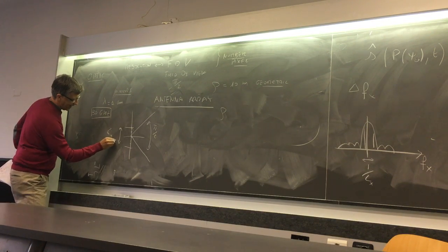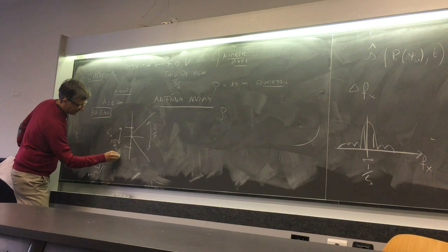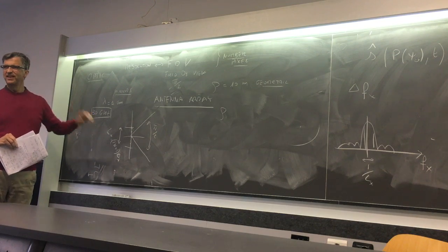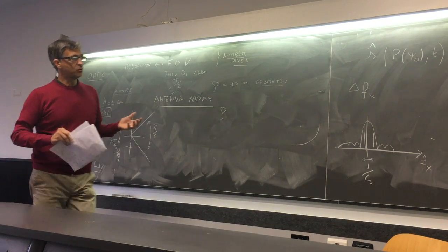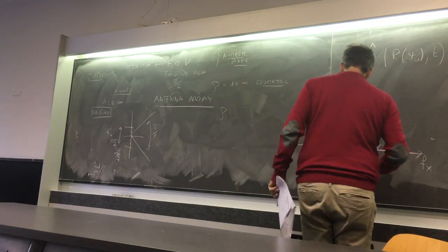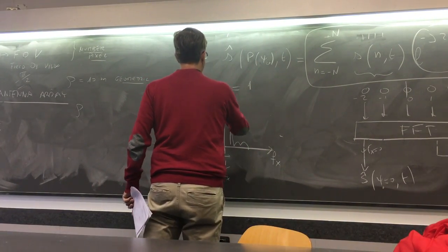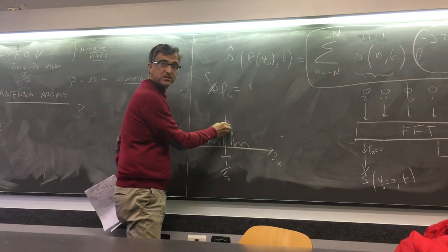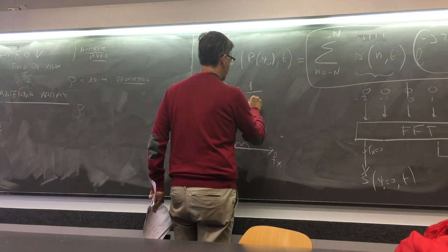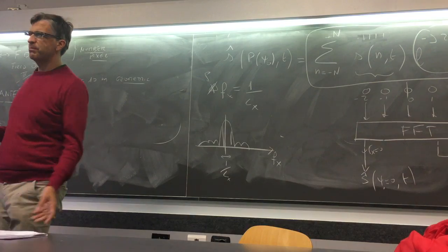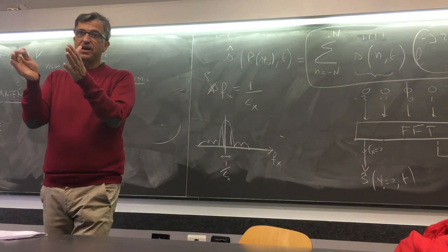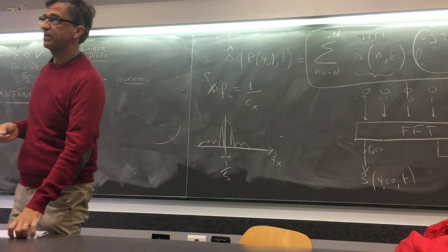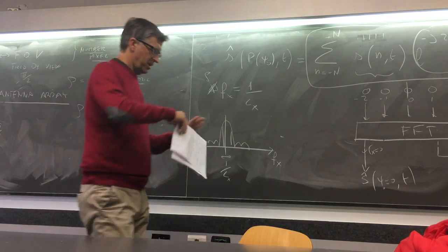It is equal to 2n plus 1 multiplied by delta x, the total number of antennas multiplied by the spacing of every element. Okay, you remember? So the resolution, let's say I want to call delta fx, is the minimum frequency width, it's 1 divided by Lx. Okay, it's like you remember when you have an observation in a certain interval T, the resolution in frequency is the inverse of the observation time. Okay, that is very simple.